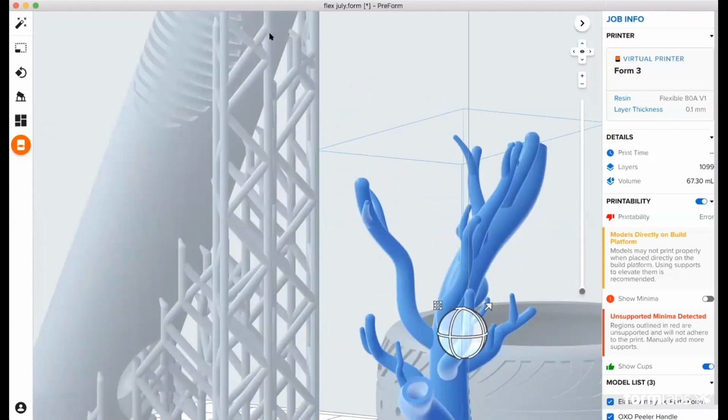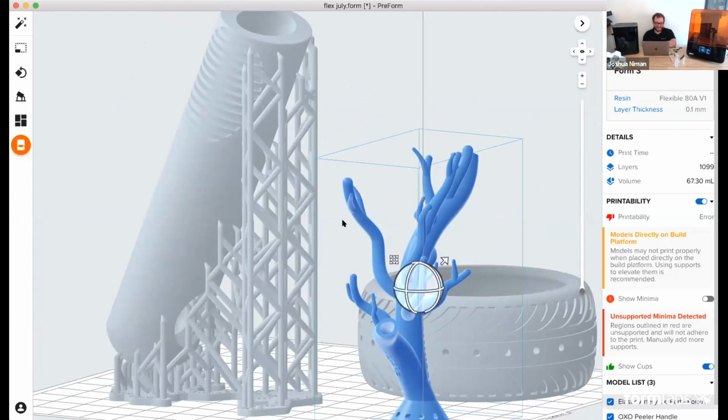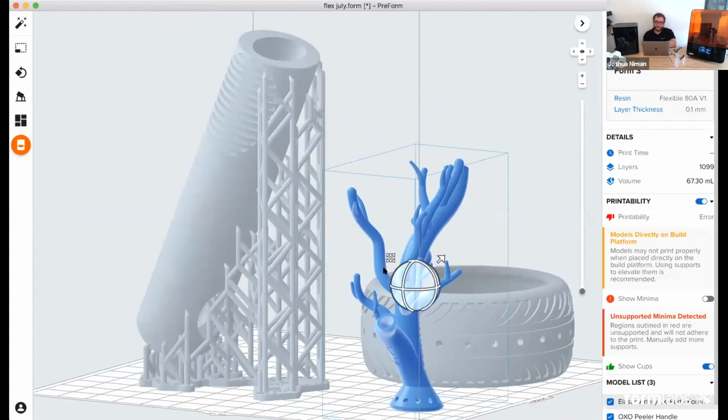I didn't, but thank you, Tim, for that prescient question. That's a perfect question, and I work for Formlabs, but I'm a user too, right? I do a lot of printing, both for customers and for myself. 3D printing's always been something I've done, and Flex V2 was a major frustration of mine with the old Flexible. It's challenging to deal with the size of the supports that we needed to get a successful print. And when you have supports in close proximity to each other, which you often needed with Flex V2 because it was sort of less stable, you'd pull them off if you could, and you'd get a big crater, or you would try to cut them off, and it was sort of a lot of material to move.